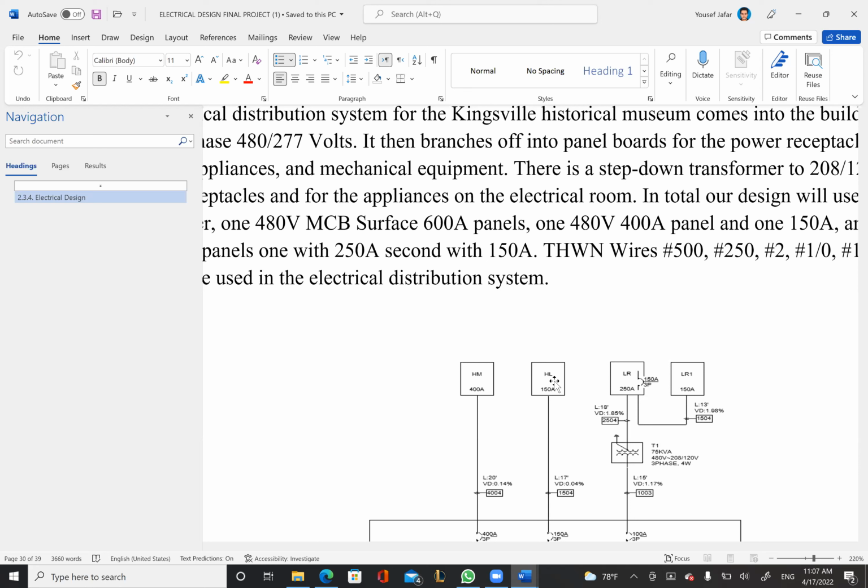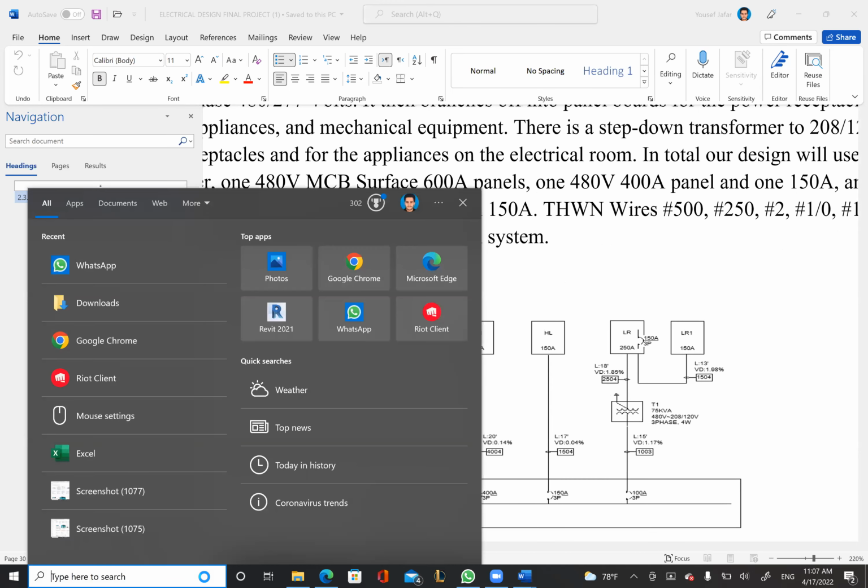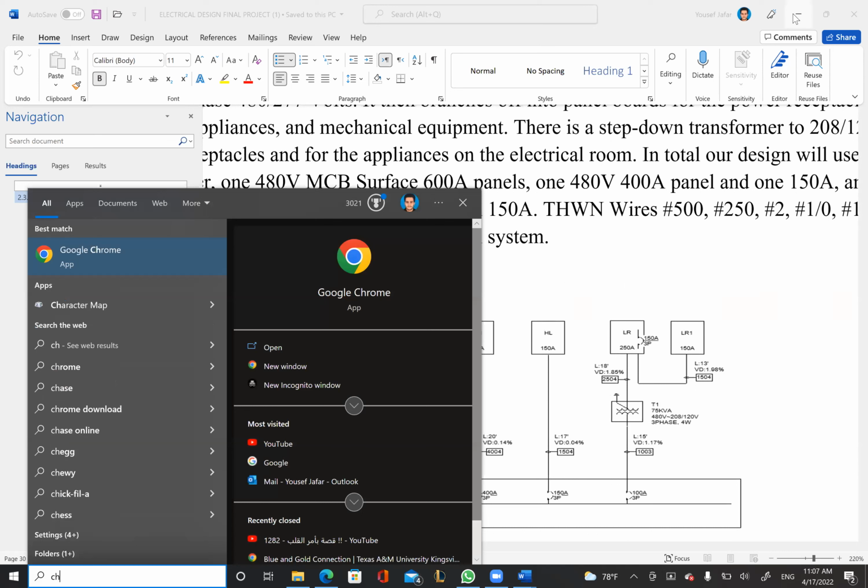Yeah, but to change that, it's easy. Just change the number and everything will automatically calculate for you. But I just want to make sure we're using the correct NEC code article. Yes, I have to change it, but I just have the picture. I don't have the whole file, I cannot change it. So if you go to table 220.12 in the NEC code, or you can just Google it online, there are general lighting loads by occupancy. Or I can share my screen right now if you want. Yeah, you can share.